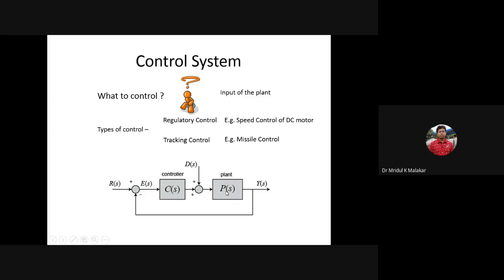Sometimes it happens that in the morning I run the control system and it is working fine, but at noon I try the same control system for the same motor and it is not working properly. Why? It is because of the change of environment. The small motor, with the small parameters you have given, may be in a hot room, at a temperature more than room temperature, or kept outside in sunlight. If you apply the same controller, it will not properly regulate the speed. You can do this small example on any day.